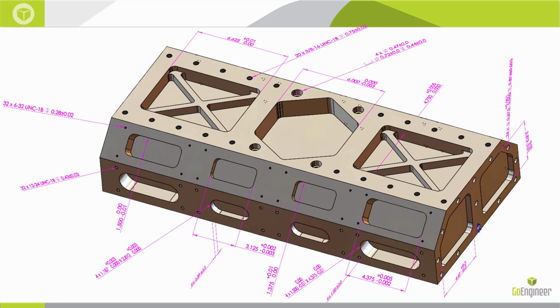When you're encountered with parts like this and you're doing the CAM programming, it complicates the CAM programming quite a bit. We see issues here with, say, asymmetrical pockets. How do we program that on the CAM side? Well, we have to adjust the offsets and basically machine to the mean. And this has all been done manually in the past. Now, with tolerance-based machining, or TBM, we can actually capture that data and use it alongside our technology database to automate a lot of this type of programming.